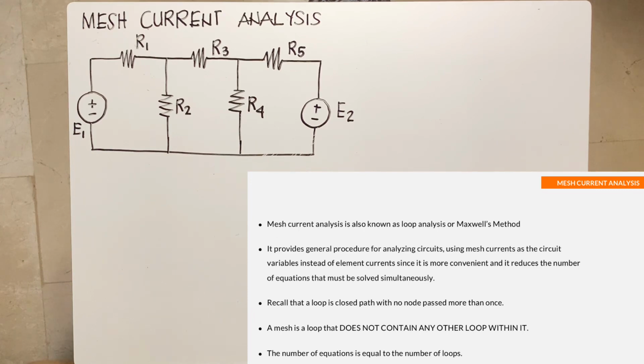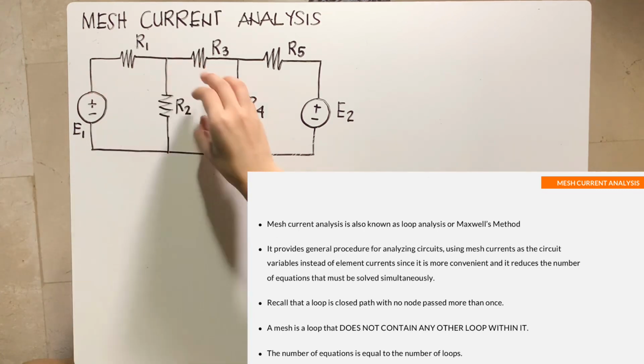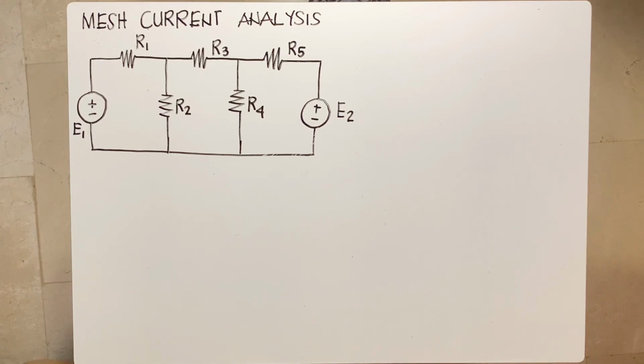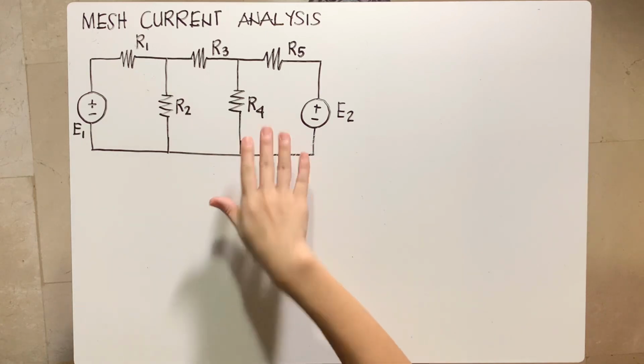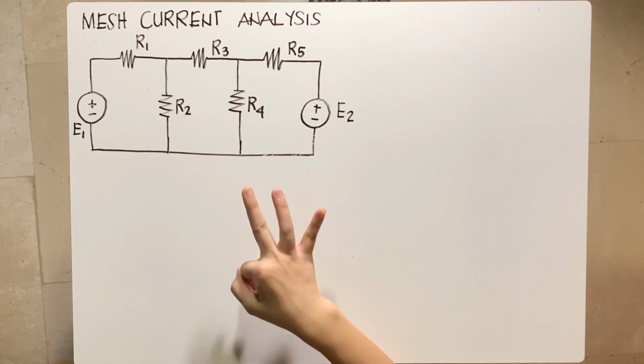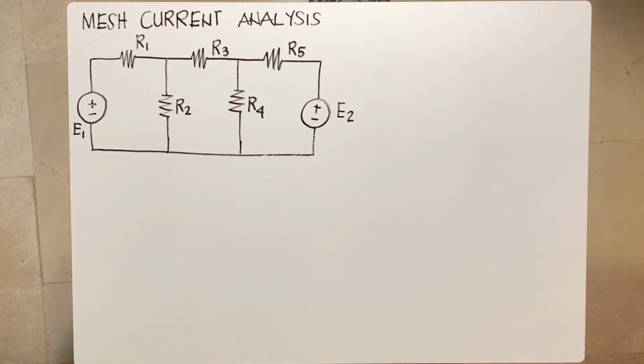So, parang kagaya ng sinabi natin nung nagki-Kirchhoff's tayo, yung mga windows ng electrical networks natin will be considered as loops. So, in this case, we will call them mesh. So, dito ang idea, kung gaano karami yung loops or mesh natin, ganun karami yung equations na kailangan nating i-prepare. If you're going to recall, kay Kirchhoff, sinabi natin before, yung number of equations na kailangan natin nakadepende sa bilang ng branches. Okay, but in here, the number of equations that you need depends on the number of meshes that we have. So since this particular circuit has 3 meshes, therefore, we only need 3 equations.